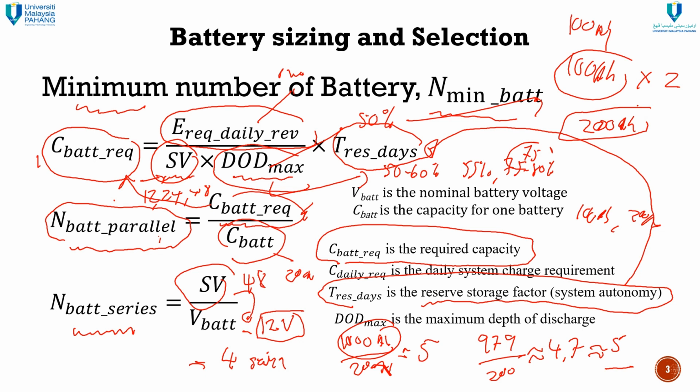You need to buy two pieces, not only one, because the DOD is there. Even though our rated capacity is 100 Ah, we can't think that we can use 100 Ah. That's the misconception. You must think that even though we have 100 Ah, we actually can use 50, slightly more than 50 Ah, maybe less than 60. That's our limitation. To be safe, we take half only, 50%.